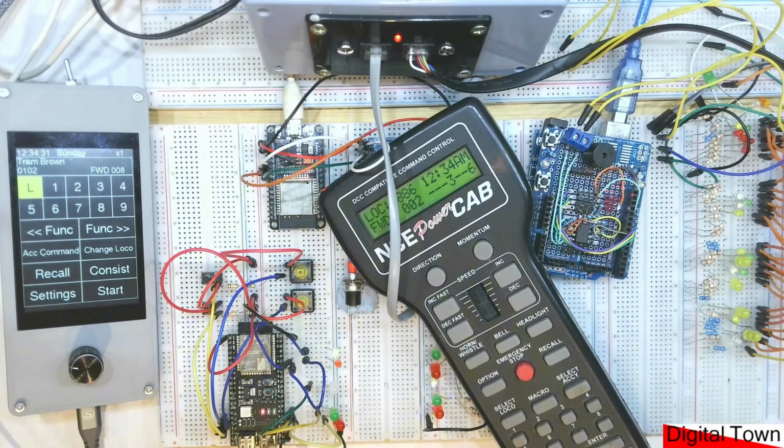Now, while we're talking about sending out commands, just a couple of things to be aware of. In nowRail, you can just use any integer for your address for your accessories. Now, that means you can have accessories into the sort of 9,000 range and higher. If you're sending commands to the NCE Cab Bus, you need to make sure that the accessory decoder addresses are below a value of 2000, and you also need to make sure that any loco decoder addresses are within the range that your NCE system can use. So you just need to check before you go and put in an address that is impossible for the unit to use.